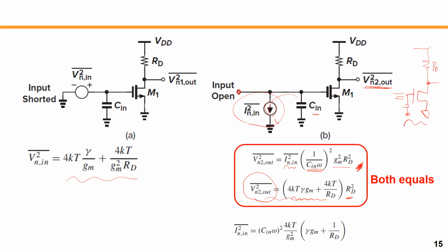For this kind of network, what we measure at the output is noise, some output noise voltage variation. It's the noise source coming out of the resistor and transistor. We can calculate the output noise voltage easily, since we have RD impedance: all the noise current density times RD square will be the output noise.